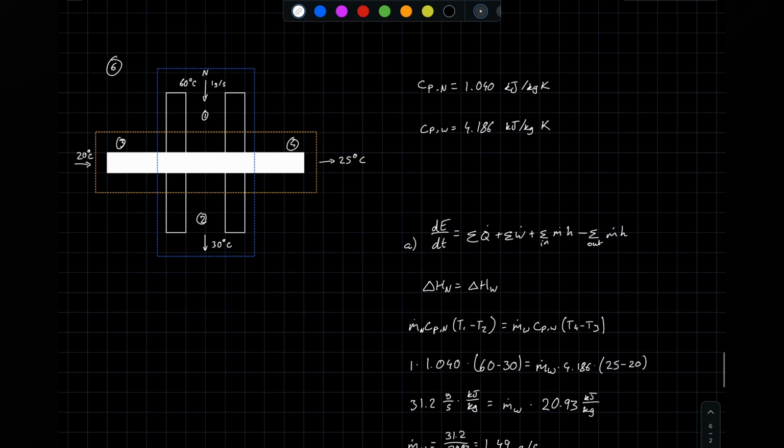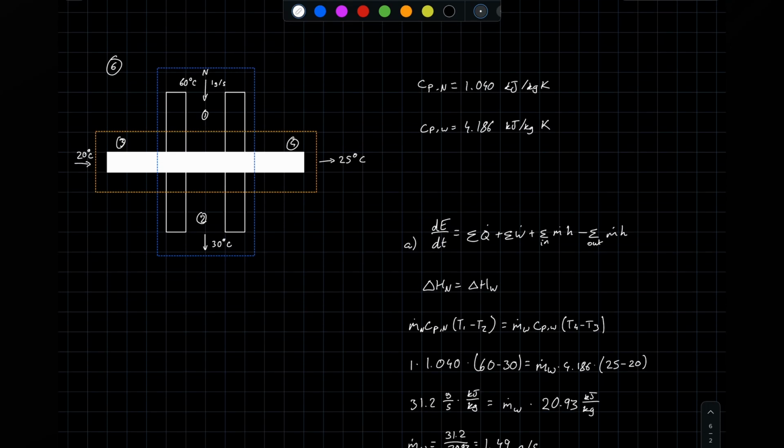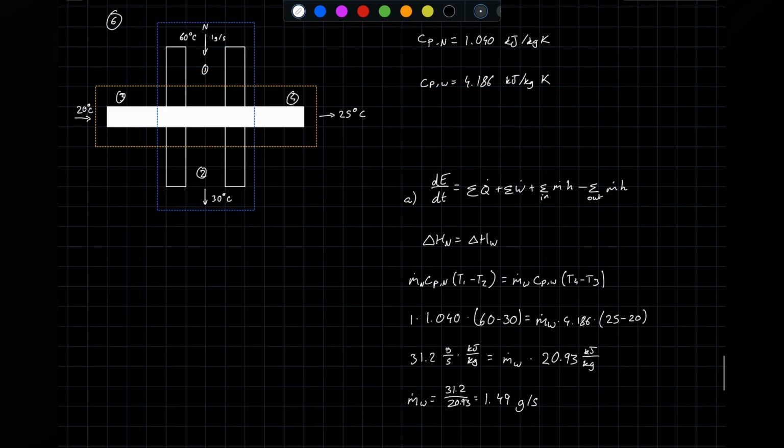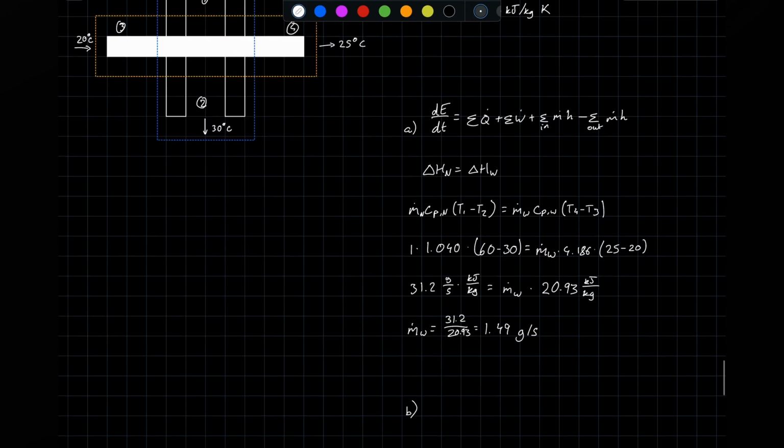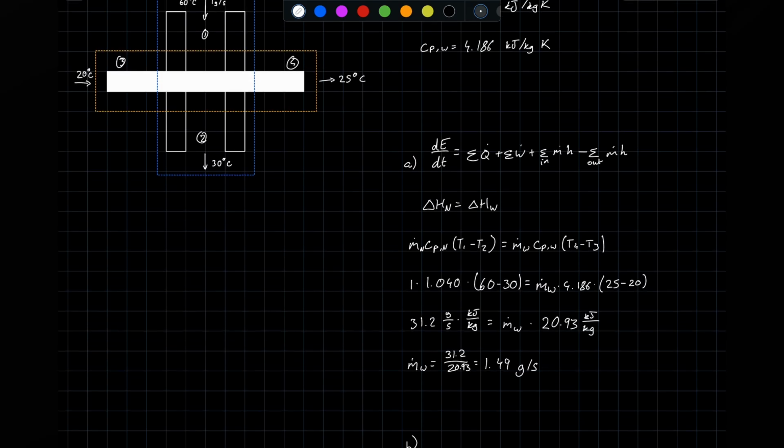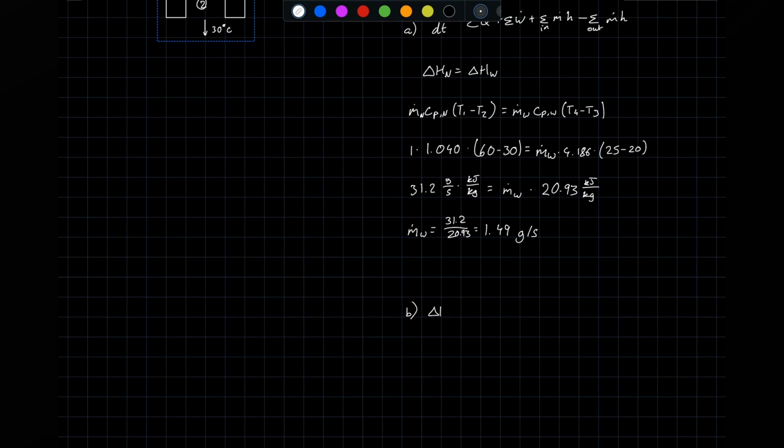So, like I mentioned before, for the blue system, we know everything. We know both temperatures, we know the mass flow, and we know the specific heat, which means we can calculate the enthalpy. And now we also have the mass flow for the orange system, which means we can also do everything with that one. And as we know, delta H is equal to Q plus work other.